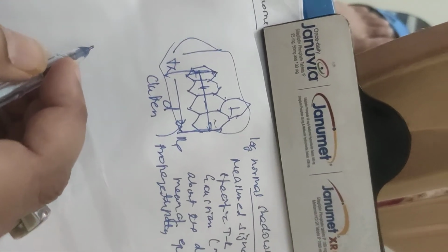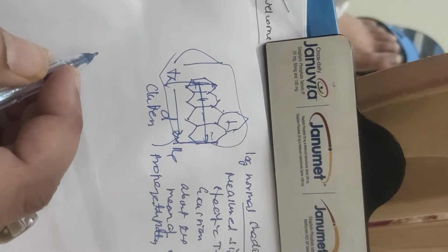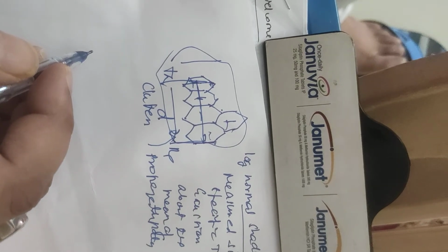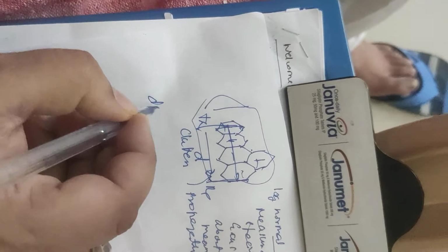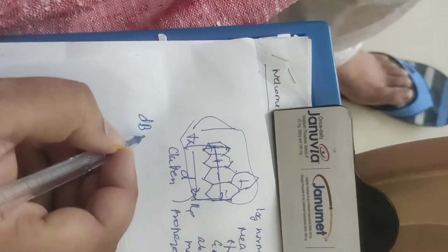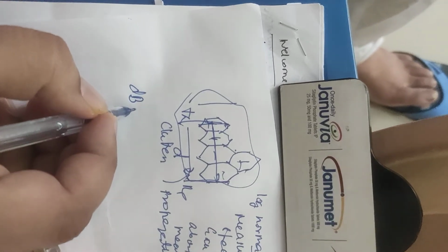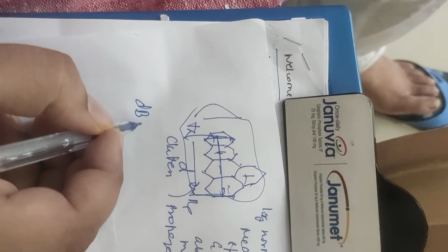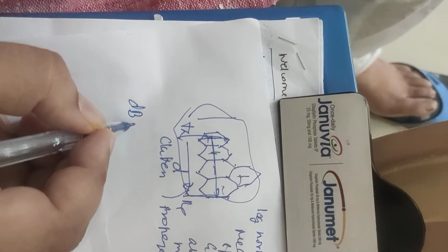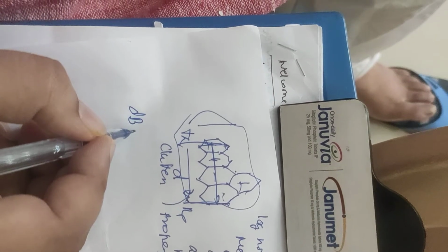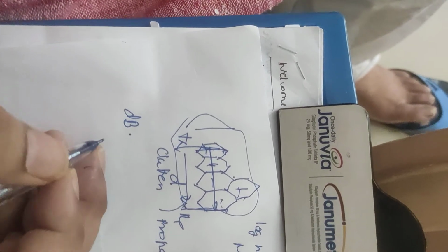The standard deviation of the Gaussian distribution that describes the shadowing also has the unit in dB. Thus the random effect of shadowing is accounted for using the Gaussian distribution, which lends itself readily to evaluations.